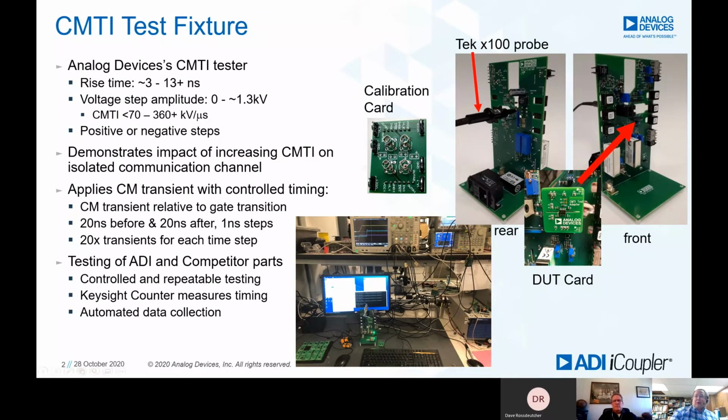As part of our studying for that, we tested over 20 different parts, both from us and our leading competitors. Basically we would apply a transient at different times, multiple times for each time step, and then sweep through the logic transition and see what happens with the part.